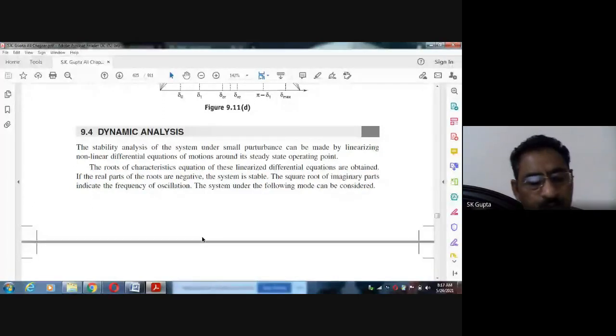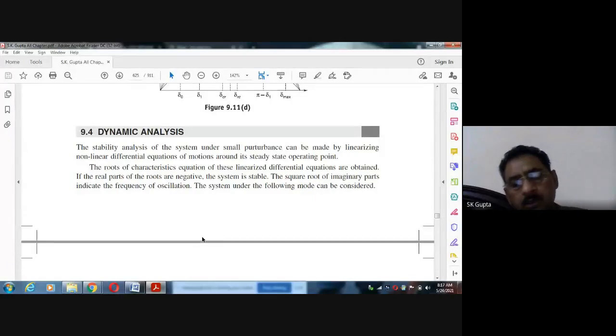if the disturbance comes, there is an oscillation around the normal position. The normal position may be the same as the initial original position or maybe a different position. Say your generator is working at a 30-degree angle. After the disturbance, the system may again work at 30 degrees or at another normal position of 40 degrees. So both are stable positions where it may work. But it is not at all at a fixed angle. It oscillates around the normal position, either 30 degrees or 40 degrees, whatever be the